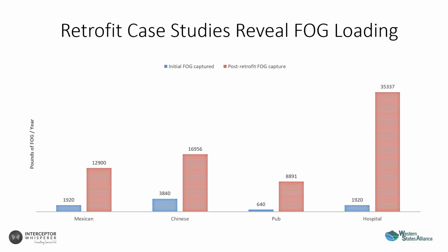So this is a graphic illustration of the difference between the old design and the current plumbing code here in Oregon and the capture rate for grease. So it does two things, though. One, it illustrates the effect of having all fixtures routed to an interceptor, and number two, having a high capacity device that captures all of that grease. Mm-hmm. So it's really a twofold strategy that makes it much more effective.